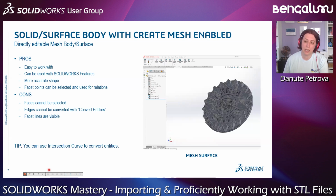What is good in this case is it's a really lightweight model, it's really easy to import in SOLIDWORKS, and you still can work with it, it's editable. For problems like convert entities, you can use a workaround with intersection curve, or choose the view you want, save as DXF, and then re-import, and you will still have the contour. You can use this also in different cases in which it's really hard to pick the contour, not only when you work with STLs. Just adjust the angle you want, save the view as a DXF file, and then you will be able to import this as a contour. I think that's one good tip.